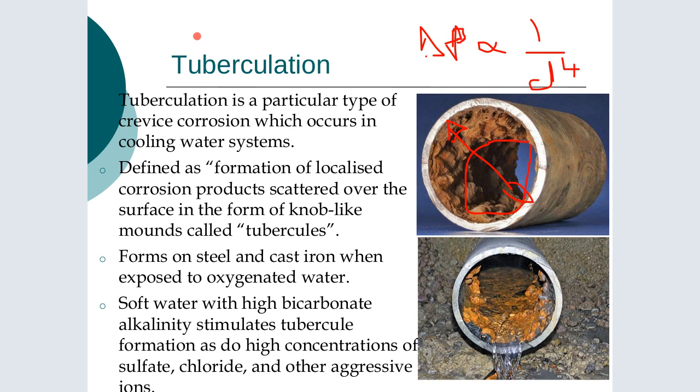And when we look at the work required to pump, you all know, of course, that the work required to pump a fluid, how much energy it takes to pump a fluid through a given pipe, is the flow rate times the pressure drop. So if we've halved the diameter, we're going to see a substantial increase in the pressure drop. So the work that our pump has to do, our energy consumption, is going to increase significantly.